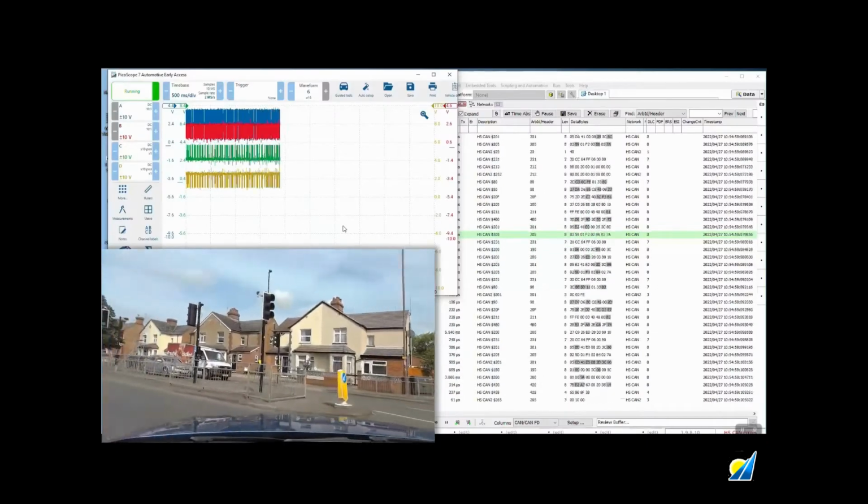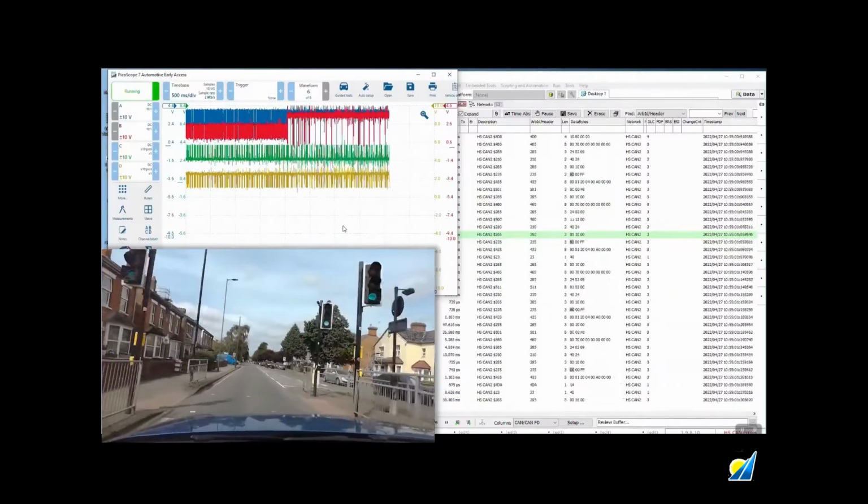So one of the fundamental checks we can do with CAN is the 60 ohm test, and luckily with this vehicle we've got 60 ohms at the diagnostic connector because we can get straight onto the CAN. We don't have to go through a gateway module. So on the road, this vehicle would play up. You'd often see multiple messages coming up, warning lights.